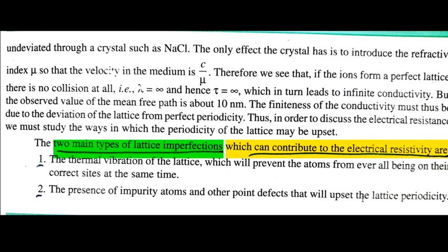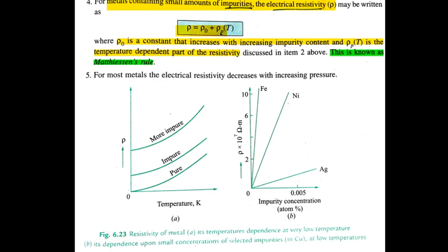So this is also to be understood: suppose an impure material is added into a crystal, or by default impurity is there, then the atomic size of your impurity differs, and therefore your lattice pattern becomes irregular. It won't have a very standard periodicity. One atom is a little bit larger. So from that point your periodicity is slightly deviated, and because of this deviation as well as the thermal vibration, there is an increment in Matthiessen's rule point number 2, that is rho p.